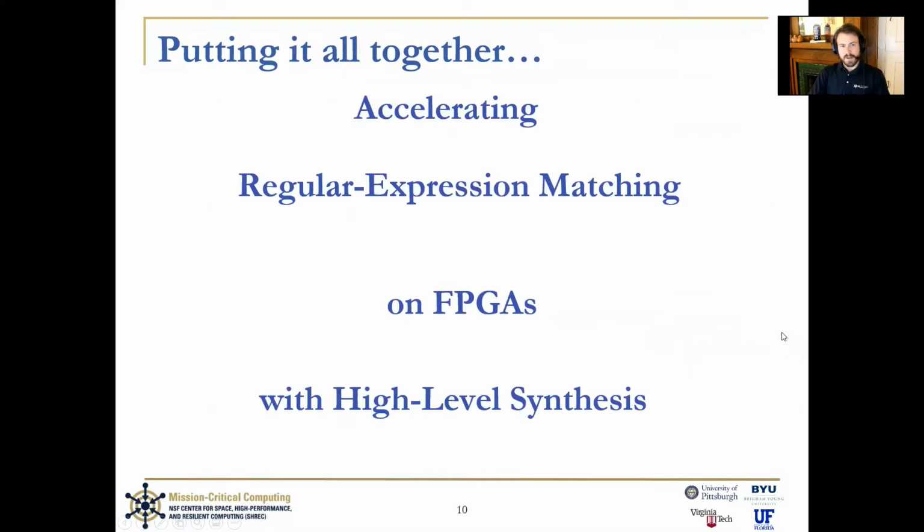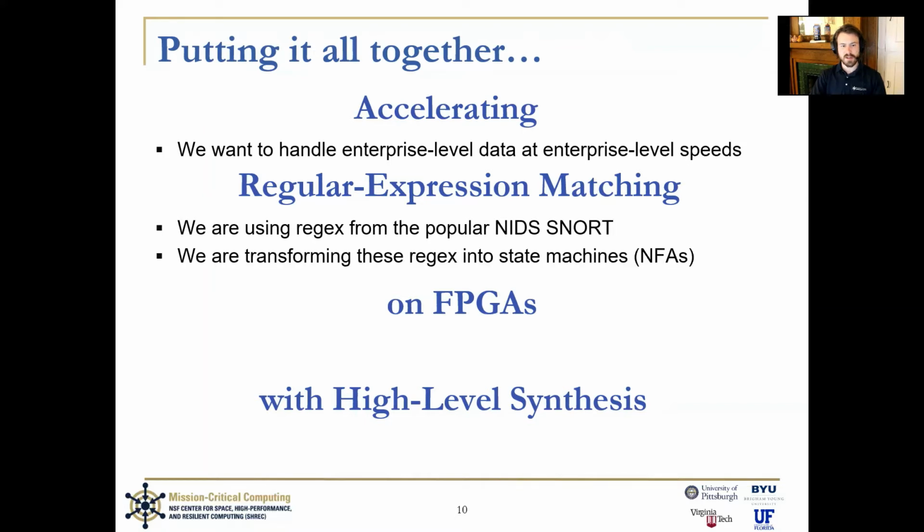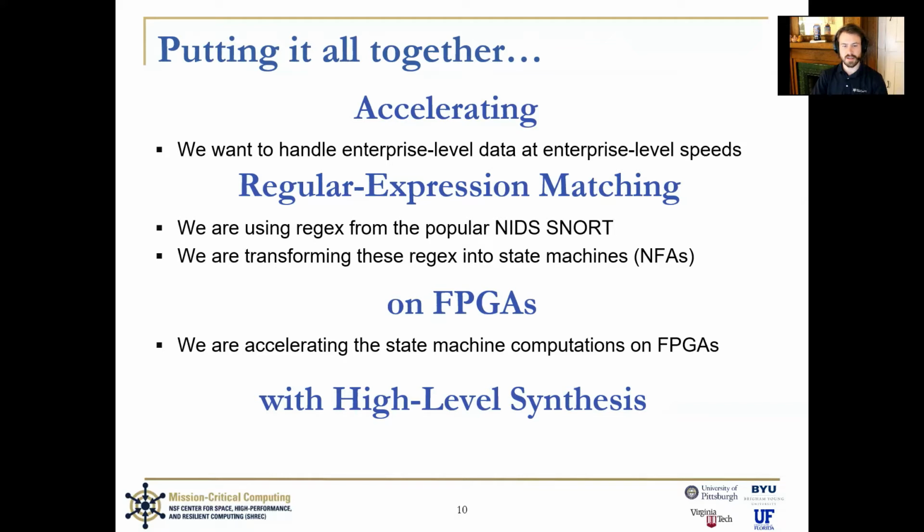So, putting these all together, we're accelerating regular expression matching on FPGAs with high-level synthesis. We want to handle enterprise-level data at enterprise-level speeds. We want to do this using regex from the popular network intrusion detection system SNORT. And we want to do this by transforming these regex into state machines for easy parallelization. We're then putting these into hardware on FPGAs. And finally, all of this is done using high-level synthesis.